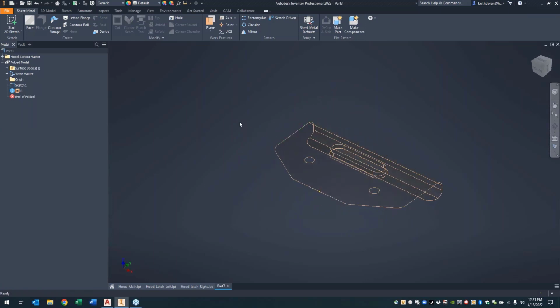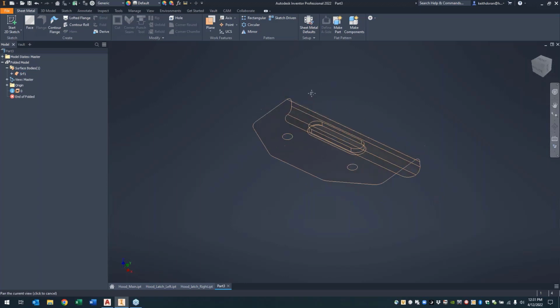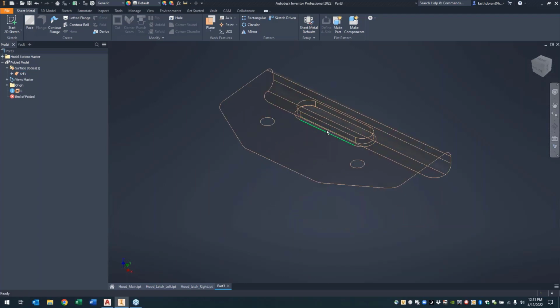If you're not familiar with surfaces inside of Inventor, it does give you essentially just an individual body. And then in this case, because of the import, it gave me an initial sketch. I actually don't need this. Surface bodies are split up based on what they are in the AutoCAD file. So I actually used a union operation on these objects in order to create one full surface.